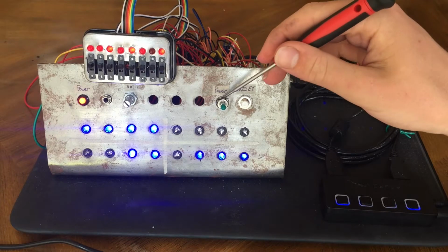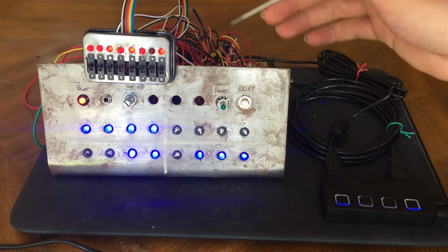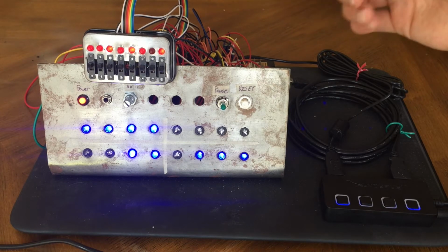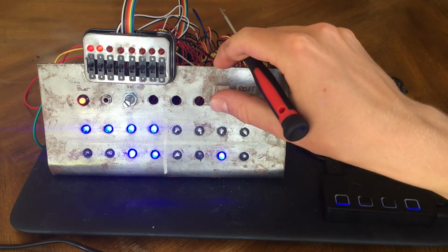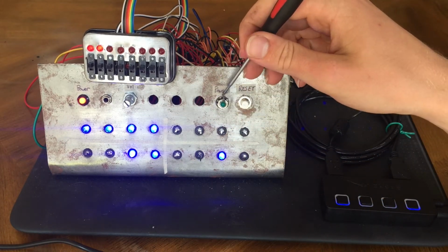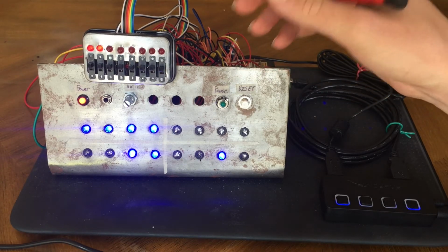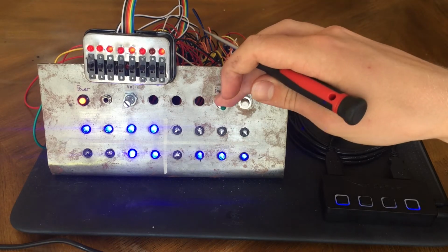The pause switch is tied straight into the ready pin on the processor. The pin on the processor is tied straight to power through a 4.7K resistor, and then when this switch is flipped, that pulls it down to ground, which tells it, hey, stop whatever it's doing, and then it'll just stay there until I release the switch.